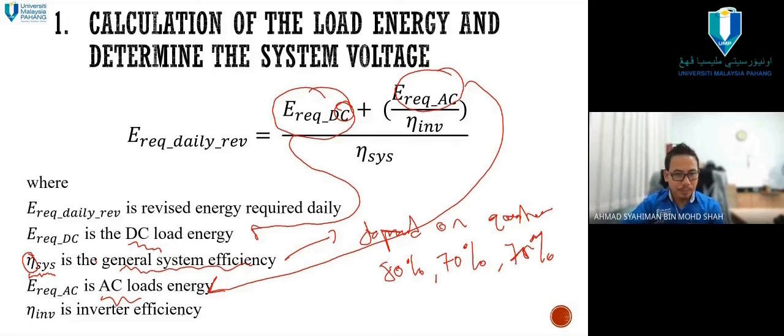Okay. And then inverter efficiency. This kind of inverter efficiency you cannot use like the grid connected. Remember, for grid connected, in most cases the efficiency is very proper, from trustable brands and very accurate, because they have a proper data sheet. Huawei, Fronius, IBC Solar, whatever. They are really proud to write the maximum efficiency in there. So they write 95%, 97%, 98%.